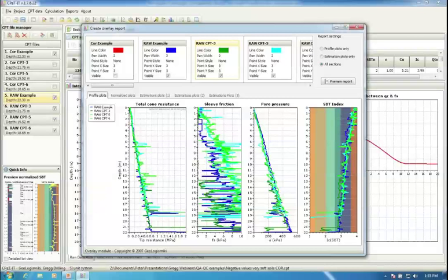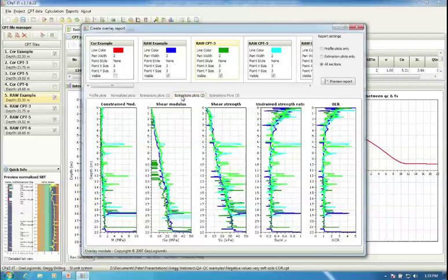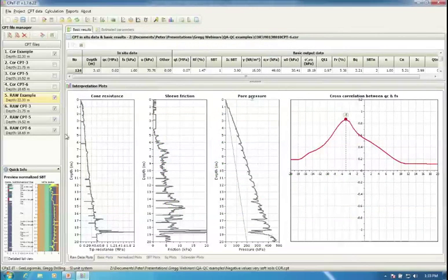So you can see that by adding a small bit here, ideally I should have put a linearly increasing value from nominally about 1 up to around 5, down at 10 meters. That's probably the correct value, but by adding just a little bit, I'm still being conservative, but at least it gets the software to work, and you can start getting estimated parameters. And here's the interpreted parameters. So I know it sounds like you're fudging the data a little bit, but you're not. You're just taking data you've got and allowing you to run computer analysis on it.